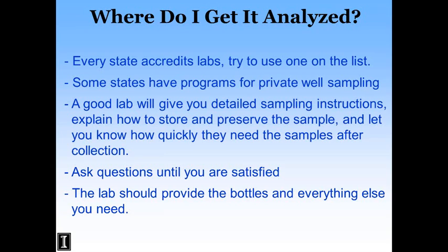So as far as getting it analyzed, once you've picked a lab or you're looking at labs, they should be able to give you the sampling instructions you need, how to preserve or store the sample if you need to do that, and let you know the best sampling procedures for collection in order to get a sample to them that's still viable. For instance, for some things, if a sample gets old, more than several days old, it can change the chemistry of the water and it's not valid anymore.